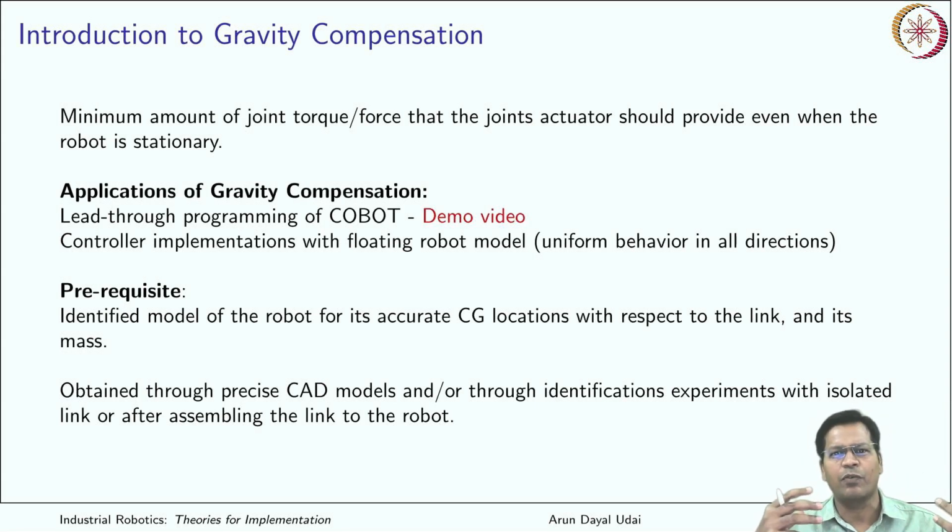Most of the time they work in impedance control, not under a position control system where you have a brake and a single-input single-output system. Rather, the controller is controlling in terms of joint torques. So it needs close attention to the torques arising due to gravity.